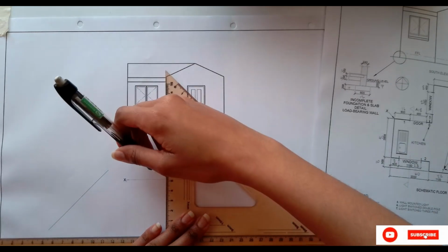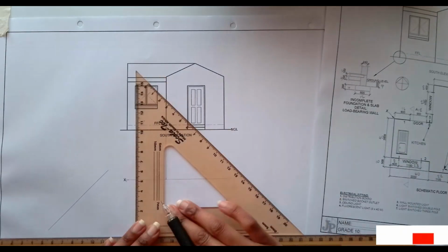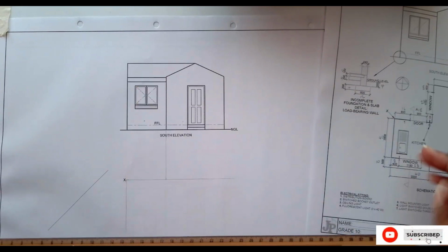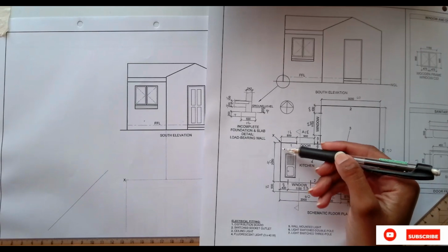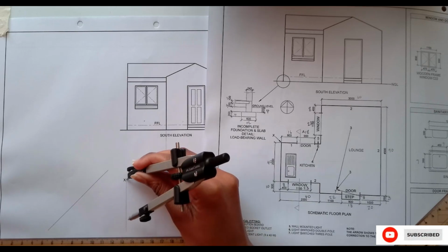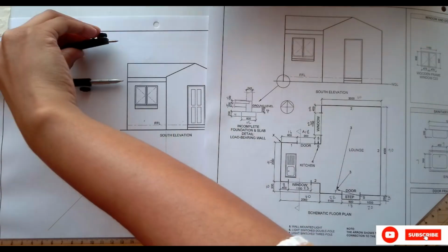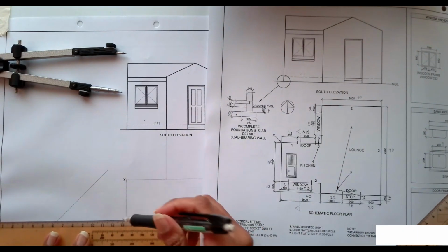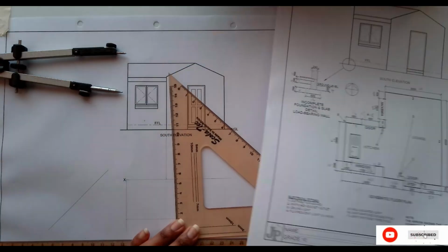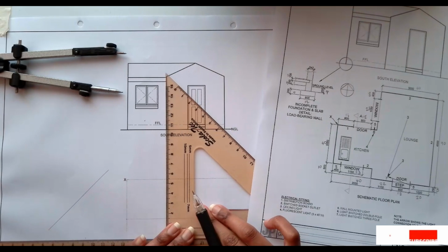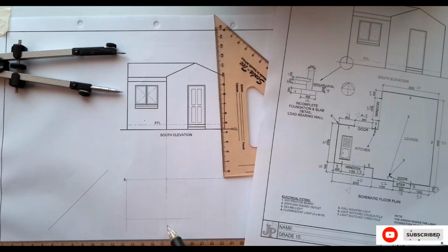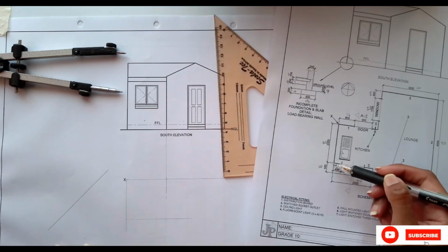Then I can project this line up, then project my other corner, another line from X down, and then we are told that the side is also 40. So my compass is still at 40. I just mark it there. Then 40 across again. So I'm just going to project that 40 that I measured down. So this is where my 40 is. Then as you can see, 10 down.